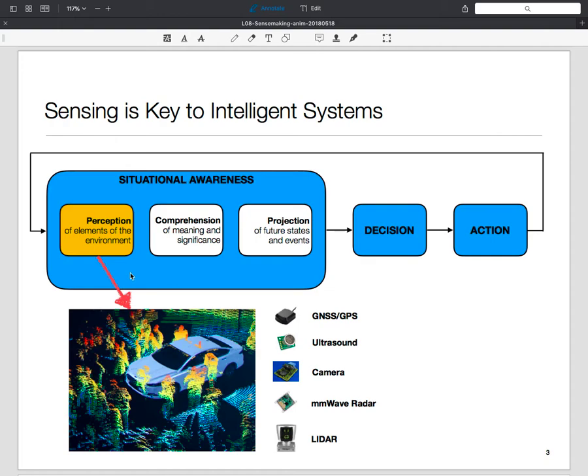Well, I mean, so does ultrasound, but yeah. Yeah, so it bounces laser. L is for the laser, so it's like a radar. Radar shines radio waves, gets it back. Ultrasound is like a sonar, sonic waves, gets the image back. LiDAR and millimeter wave radar do the same thing. The difference though is that these are very pencil thin beams. They really are not like a radar, which sends out a signal that just traverses around and bounces back. LiDAR is laser, so it's a very sharp beam which goes out. Millimeter wave is in the same vein.